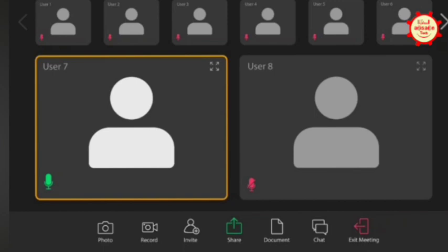Normally this thermal design is done by HTRI. They also give one DXF file, right? So you can use that. Yeah, we are using that one also. But I'm just thinking about an alternative option. Normally we get the DXF file, we paste it in the tube sheet, then the drill happens. It takes only 10 to 15 seconds.